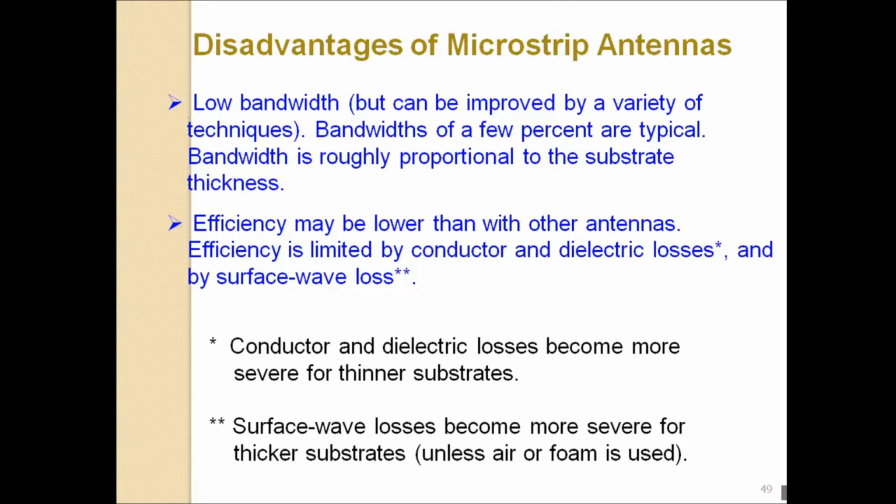Creating a slot over the antenna, a U slot or an F shape of antenna, increases the bandwidth, because the microstrip patch antenna has a narrow bandwidth. So, in order to improve the bandwidth, we can make many changes in the structure of the microstrip patch antenna, and also in the selection of the dielectric material.